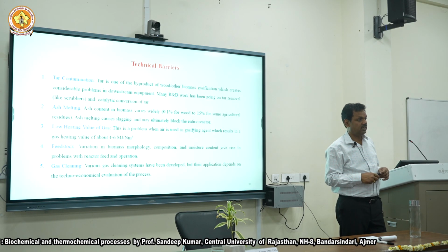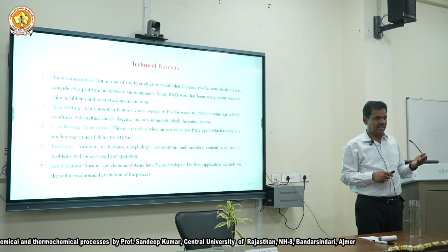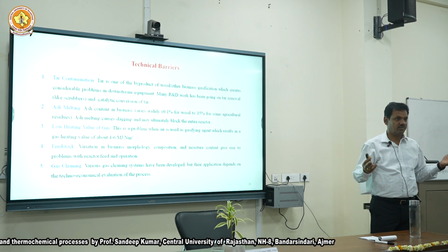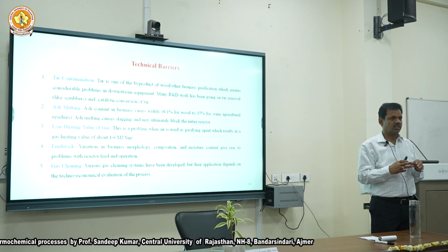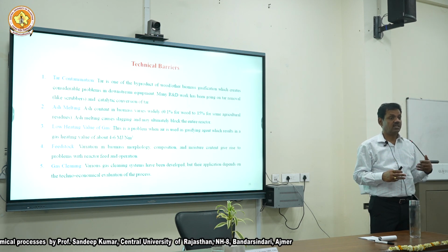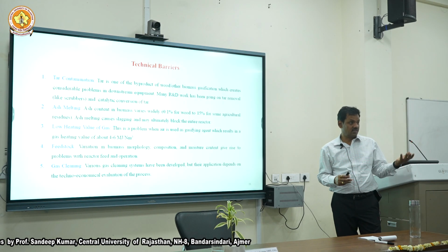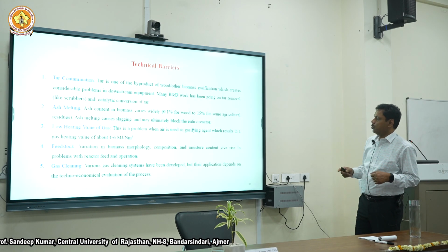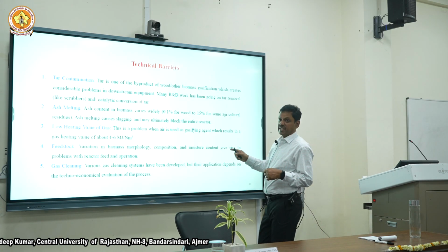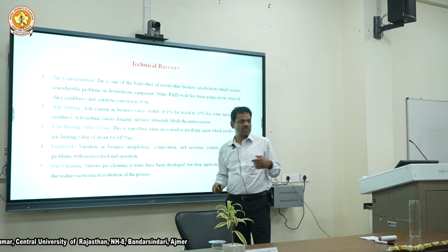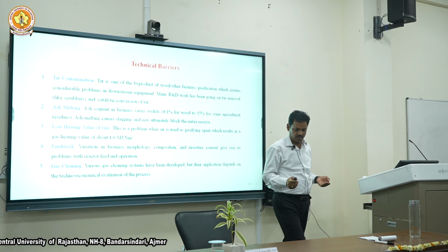Ash melting. We are talking about 800, 900 degrees Celsius. So the ash, which is sodium, potassium, silica, will fuse together. And in the gasifier they will form clinkers and other things, and they will destroy it. Low heating value of the gas. We just talked about it. Gas cleaning is needed because tar will come and many other things come.